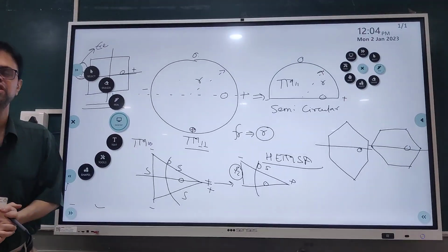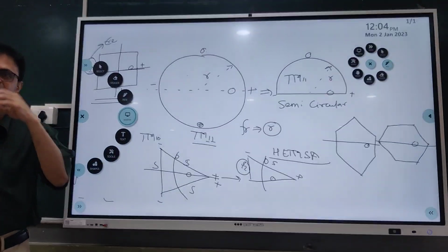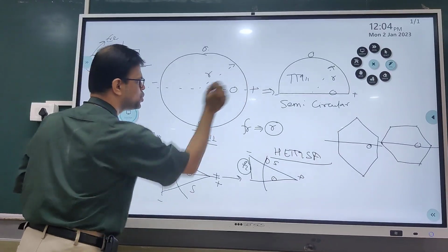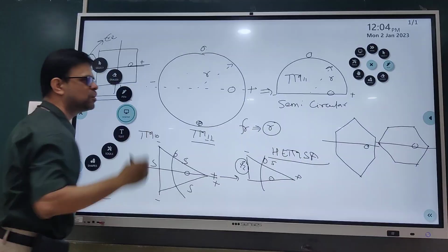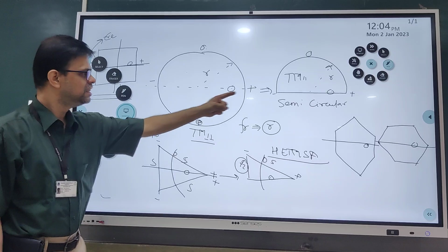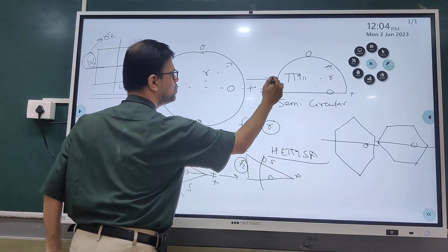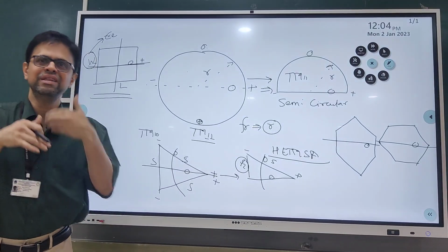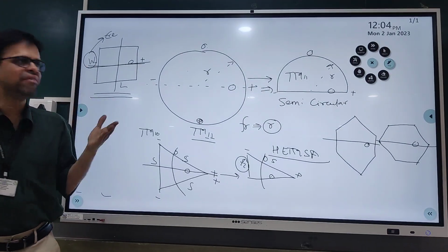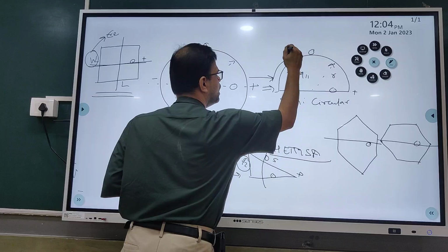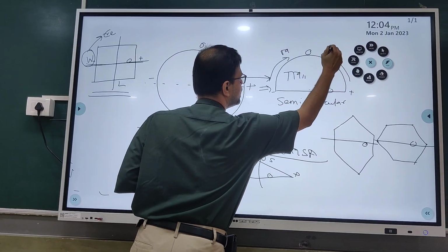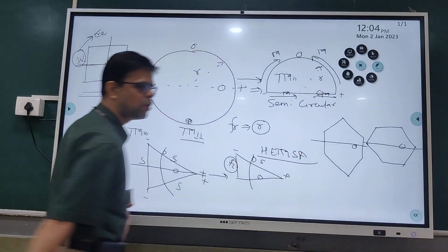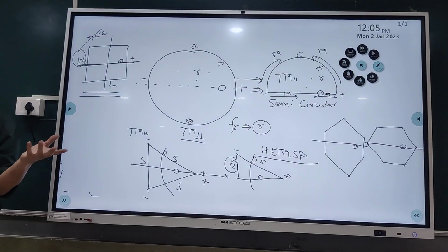Why does cross polar radiation increase? For that, you always need to consider the distribution of fields around the patch geometry. Here, the distribution of field is symmetrical with respect to the circular patch, whereas this distribution, going from here to here, has been disturbed. That actually changes the equivalent magnetic dipole model around the patch geometry. See, this is the equivalent magnetic dipole model which is drawn with respect to the fringing fields.